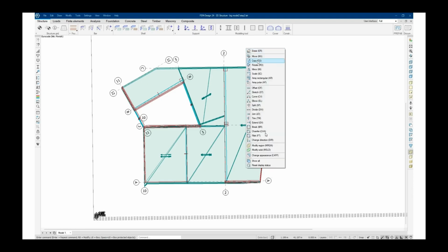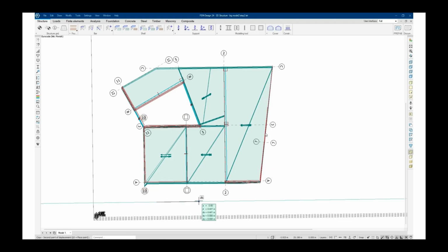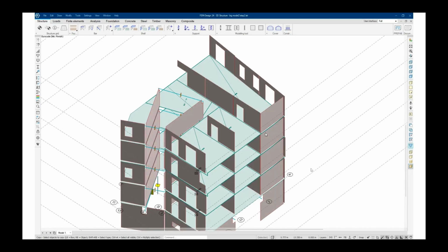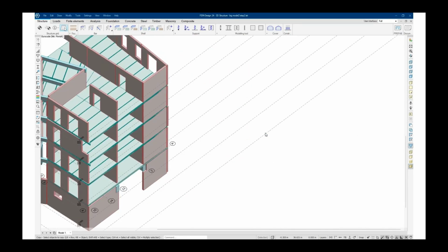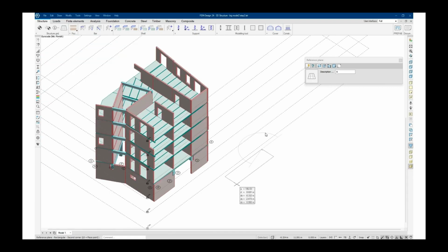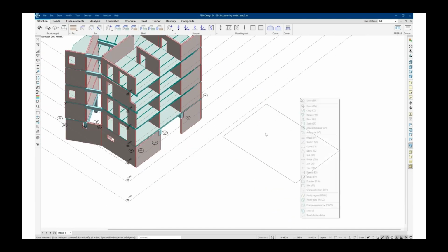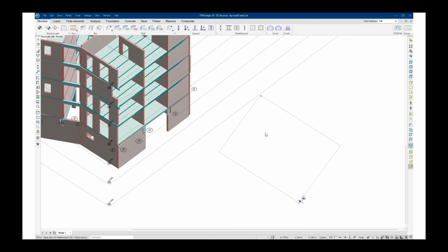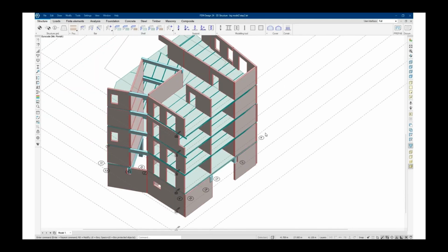And my favorite way to define axes is by copying. You just make one axis and then you copy it, and it's really fast to put one-direction axes in your model if you copy axes. So basically, I would say that for element prefab frames, making the axis system shouldn't take more than 5 minutes. And this is the example of a reference plane. You can see that it can be in any orientation. You can even rotate or stretch those planes afterwards. So we can rotate that and put it in the final place. But there you have to be really careful that they are in the right location when it's an inclined plane.